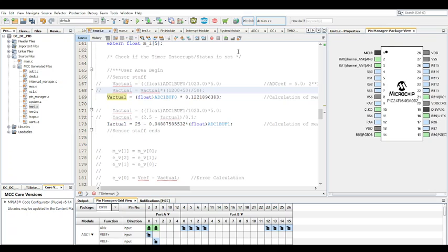I assume you want to step down the voltage before you send it to your microcontroller. So let me not use the words big resistor and small resistor. Let me say R1 and R2. R1 is the top resistor that's connected to the voltage source you're trying to sense.